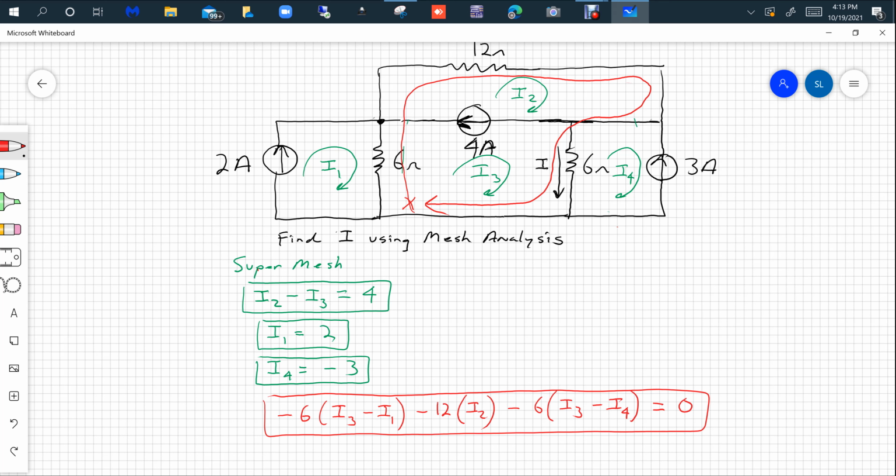I tell everybody, just get them in a standard form. Once you get these network equations or these system equations, they're real easy to get. Don't try to use algebra to solve them. I'd put the first one in a standard form, and I'd say, that's a 0 I1, plus 1 I2 minus 1 I3 plus a 0 I4, because it's not represented, equal 4.